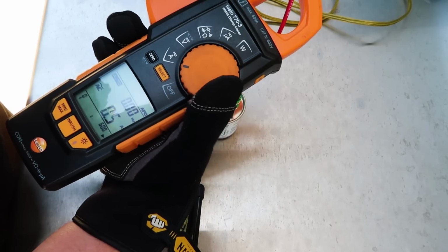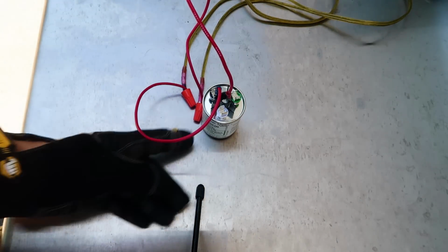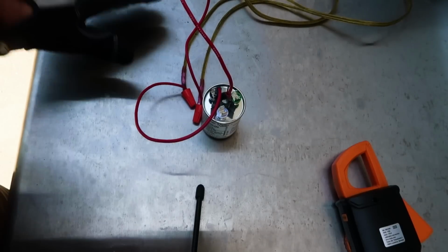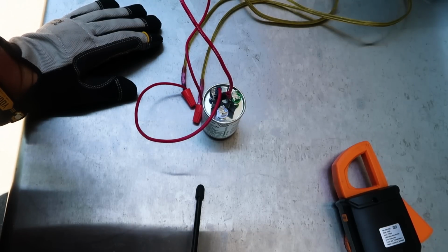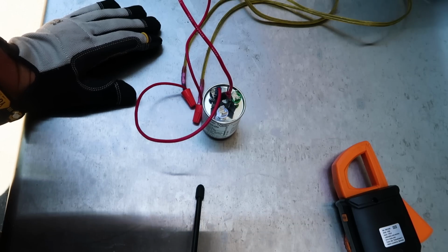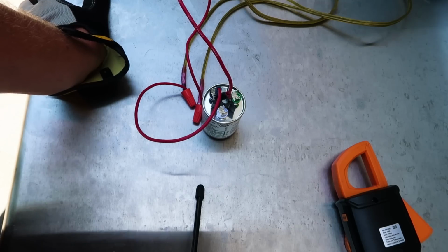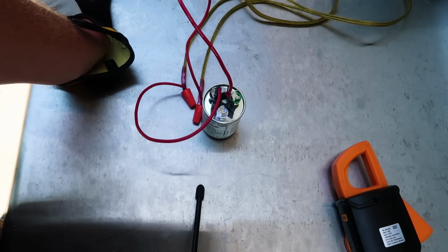It's drawing half an amp. Drawing half an amp? How's it drawing half an amp? Is it actually creating any heat? Is it doing any work? The answer is no, it's not. That is all reactive power, which means that it's creating an out of phase current, so it's storing and discharging. It's taking from where it came from and then putting it right back again. That's what a capacitor does. If you imagine it almost like a balloon, it fills up and then discharges, fills up and then discharges. That's sort of what it's like.